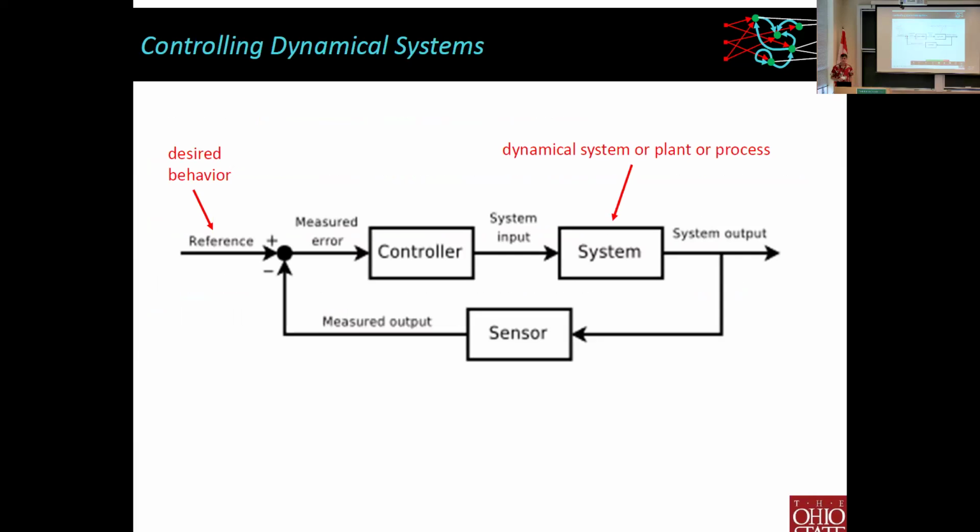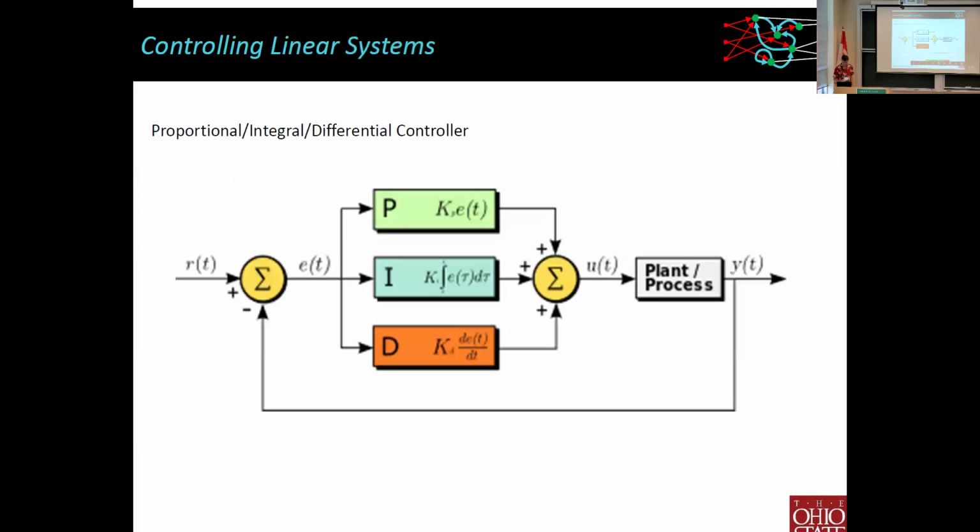So the general idea of feedback control is that I've got some kind of system. Sometimes this is called a plant in the control literature. This plant generates signals that hopefully you can poke and prod, attaching some sensors to it, so that you generate signals that you can then use for estimating the state of the system. You then compare that to the desired behavior that you would like the plant or the system to follow, and you design some kind of controller so that you drive the system to the state that you'd like it to go to. So this is a closed loop feedback type system.